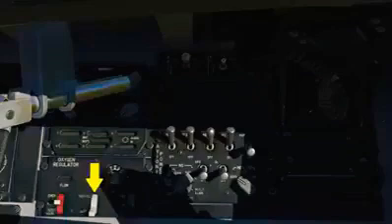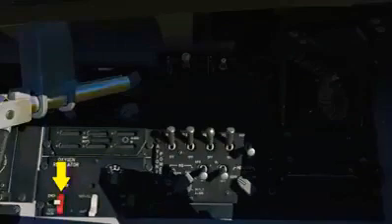kit. The oxygen regulation panel controls the flow of oxygen to the face mask. The supply lever enables the system to be off, supply air in the on setting, or it also includes a pressure breathing for G with the PBG setting. The dilute lever can be set to normal O2 mixture or 100% O2. The emergency lever can set the system between emergency, normal, and a mask test. At the top of the panel is a gauge to indicate the PSI in the O2 system.